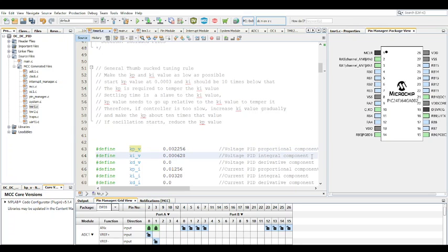So let me put it this way, right? You must always try to maintain the KP at least 3 times bigger than the KI. Just keep that in mind. Sometimes it can be 2 times bigger, but I usually don't like to risk that. So I just like to keep the KP 3 times bigger than the KI. In this scenario, let's say it's too slow, so you increase the KI slightly and increase the KP proportionally.